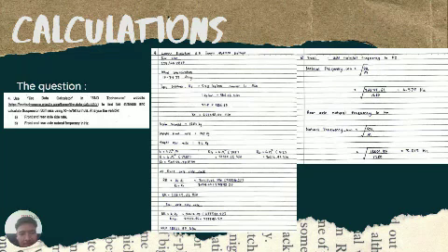So we put in the amounts, then we calculate and we get the ride rate for the front axle as 268,363.62 Newton per meter, and the ride rate for the rear axle is 118,601.97 Newton per meter.